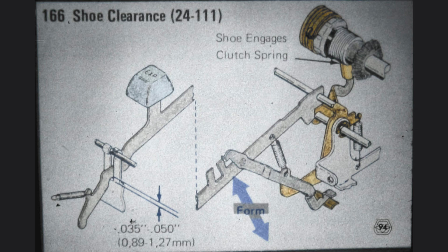The last key on the right-hand side of the keyboard, which was affected by the adjustment of the keylever up-stop, is the express backspace keylever. Notice that in this case we are not told to use the horseshoe adjustment. By allowing additional downward travel for the keylever after the clutch shoe has engaged with the spring, we are able to obtain the correct amount of shoe pressure on the carrier return clutch spring when the express backspace key is fully depressed. A more detailed description of this adjustment is found in our training program 10.5.